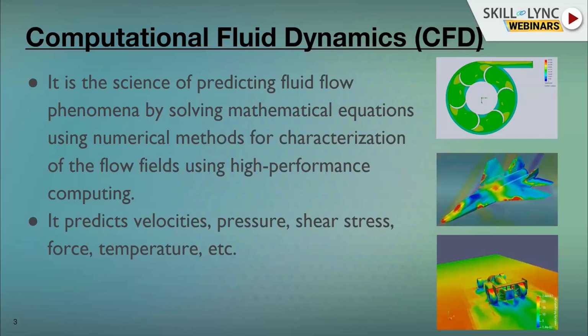So in those scenarios, we go to numerically solving these governing equations using a computer. You might know this, but I will still give a brief introduction. We discretize the fluid domain, or the problem domain, and approximate the partial differential equation by algebraic equations, and we solve for each cell in the discretized domain. There are different discretization methods, like the finite volume method, finite difference method, finite element method, or lattice Boltzmann method, etc.